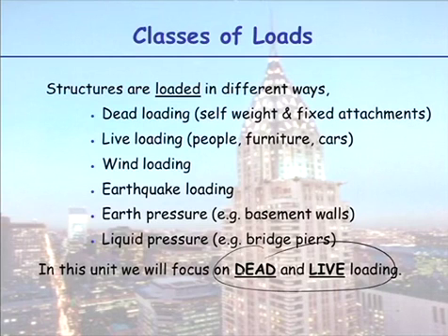Dead loading being self-weight or permanent fixtures, such as the chairs in this room. They are bolted in, so they are considered permanent loading, so dead loading. You are live loading, you are transient, you can move in and out. If the chairs were not fixed, if they were just tables and chairs, such as up here, the chairs here, the furniture would be considered live loading because it can be moved around.